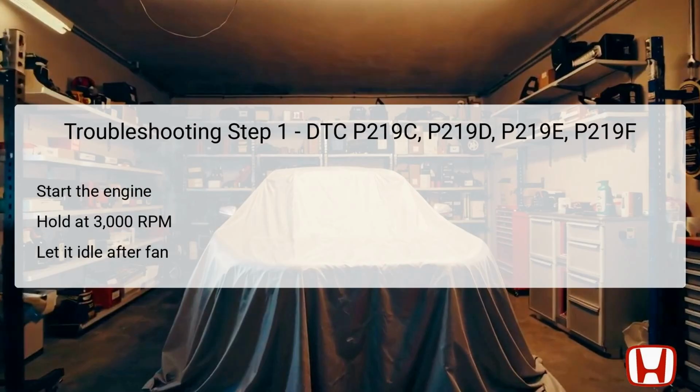The first step in troubleshooting the DTCs P219C, P219D, P219E, and P219F involves starting the engine and holding it at 3,000 RPM without load. This initial step allows the engine to reach optimal operating temperature and pressure, ensuring that all systems are functioning correctly.